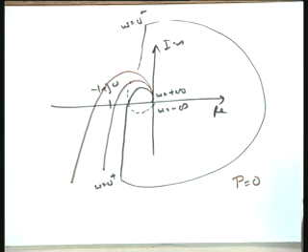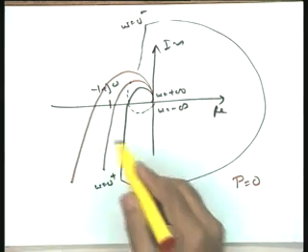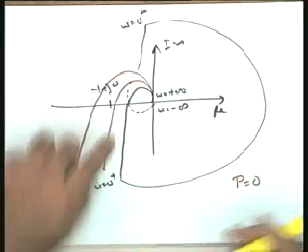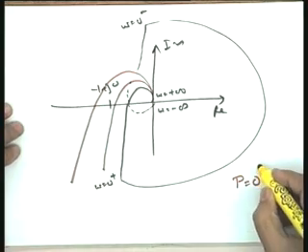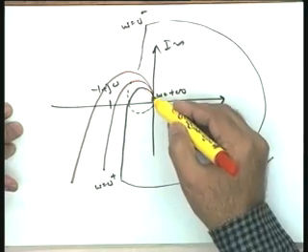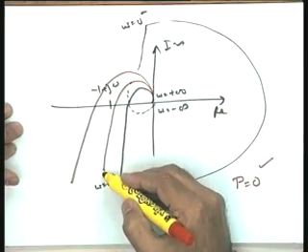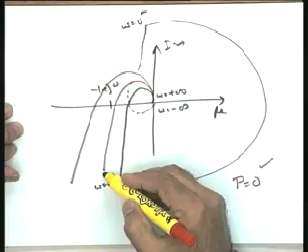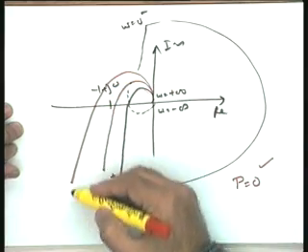Please see, stability is definitely with respect to the number of open loop poles in the right half plane. So, if I am analyzing the stability with respect to the Nyquist plot given to you, I assume that P is equal to 0, and therefore, this system is more stable, this system is closer to instability or sustained oscillations, and this system becomes unstable.